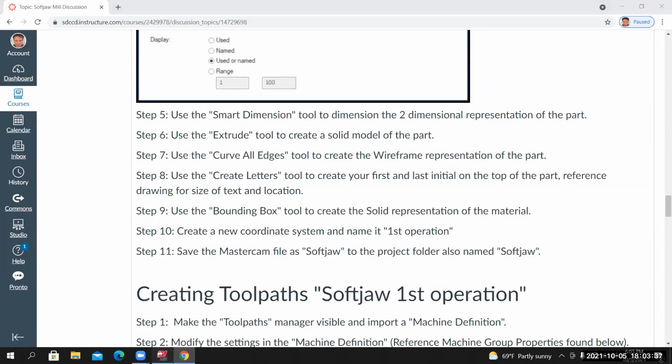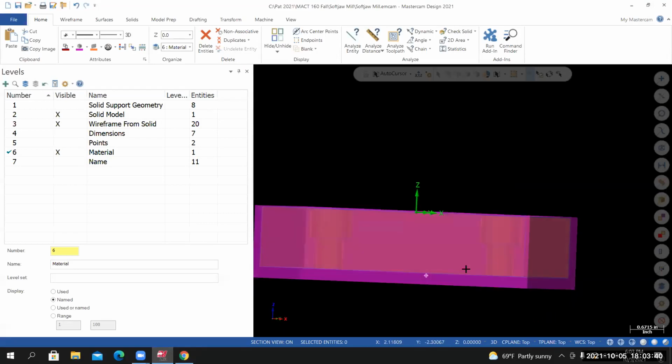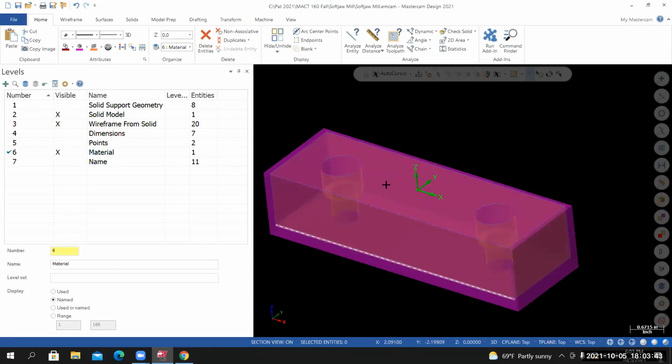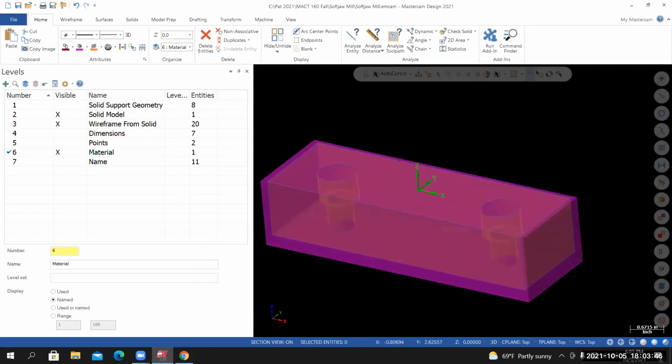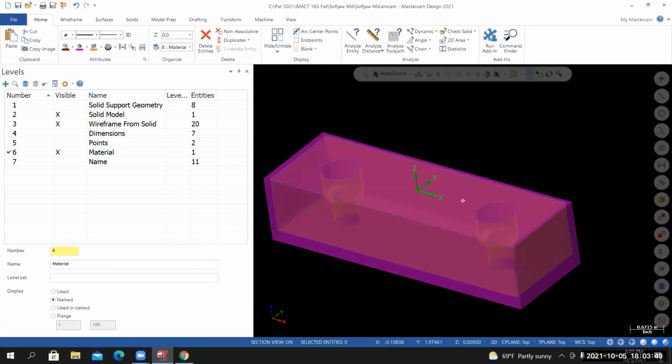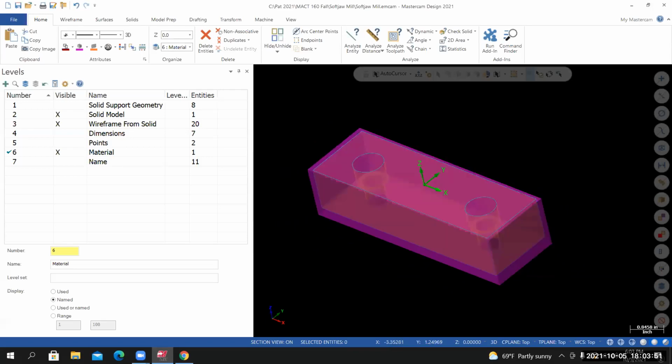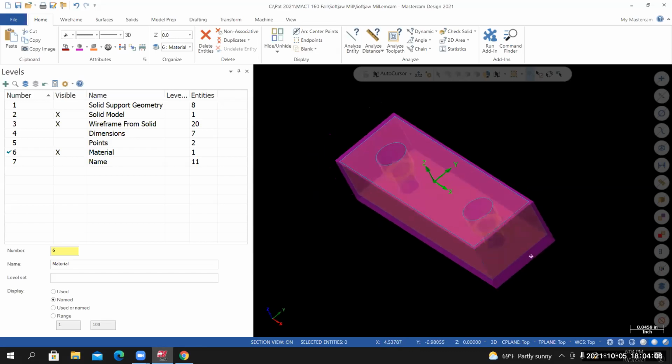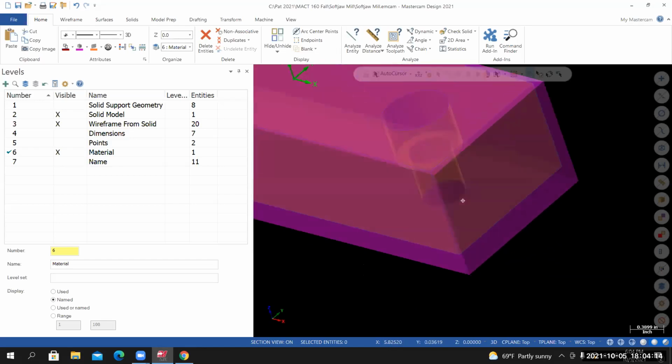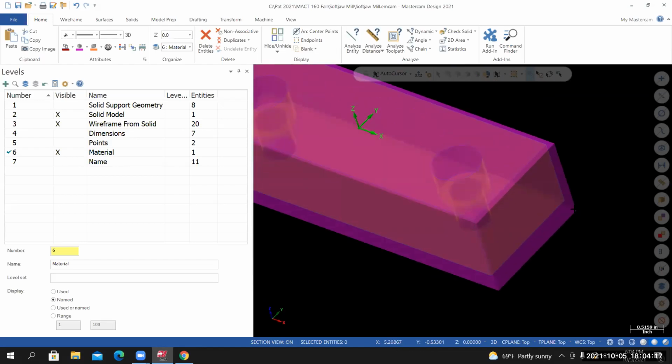Okay. So if you look at the current coordinate system, it's centered on the top face of the part, and it's actually recessed into the material. So it wouldn't be easy to establish our origin based off of the coordinate system that's embedded into the material. So what I would like to do is reposition it so that we could access the origin with an edge finder or a probe. And what I'm thinking is this corner right here. It could be placed anywhere on the material, but for repeatability reasons, I'm going to place it right here.